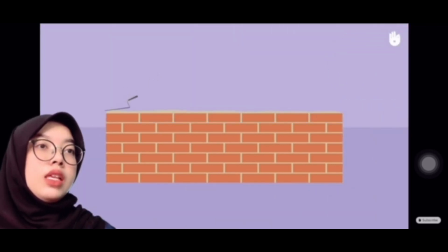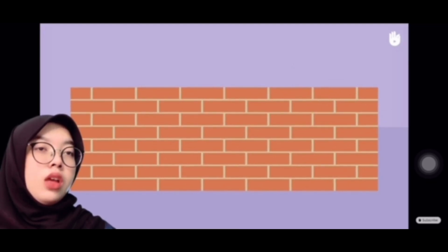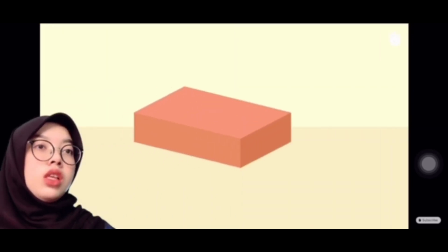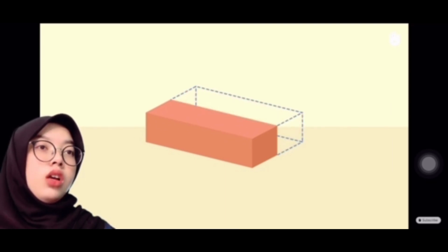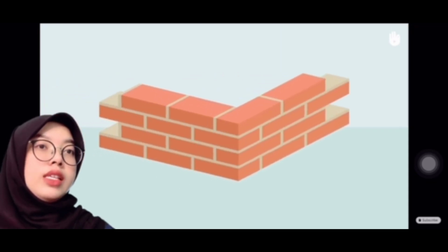A mortar bed is the layer of mortar on which a course of bricks is laid. A perpend is the vertical layer of mortar at the joint between two bricks. They ensure that the bricks in the same course are held together. A queen closer is a brick cut in half lengthwise. The quoin is the corner brick where two walls intersect.